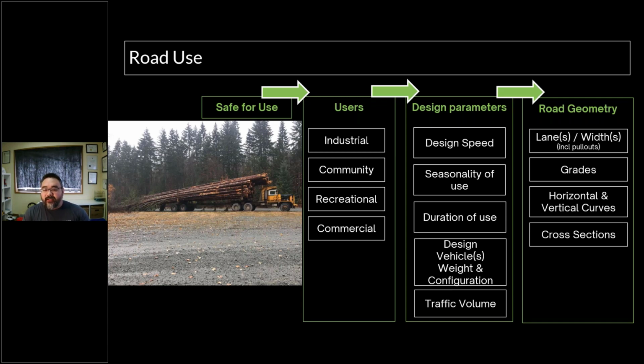slight changes. And we'll talk about this a bit later, but for example, changes in climate, or changes in some of the regulations that I mentioned before, or if you're stepping from one watershed to the next, maybe it's a community watershed, or maybe you're getting closer to a lake or some feature where the recreation use changes and it's way higher. Well, that's going to change how and maybe where you put the road, because you're going to expect those users. So, that's kind of on the ground.